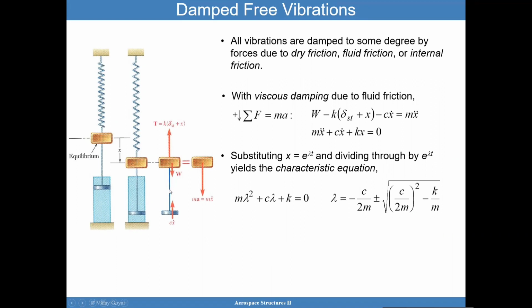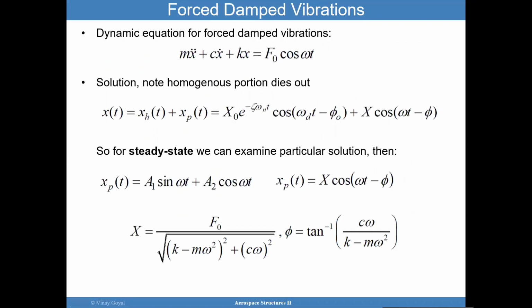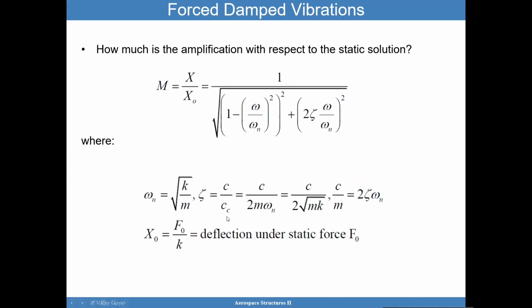But if I'm interested in understanding how this harmonic motion amplifies how much this box really moves, then we could look at that. We can determine that because X here is equal to this, and I can determine the amplification by dividing X by how much deflection I would have gotten if I applied that force F statically.